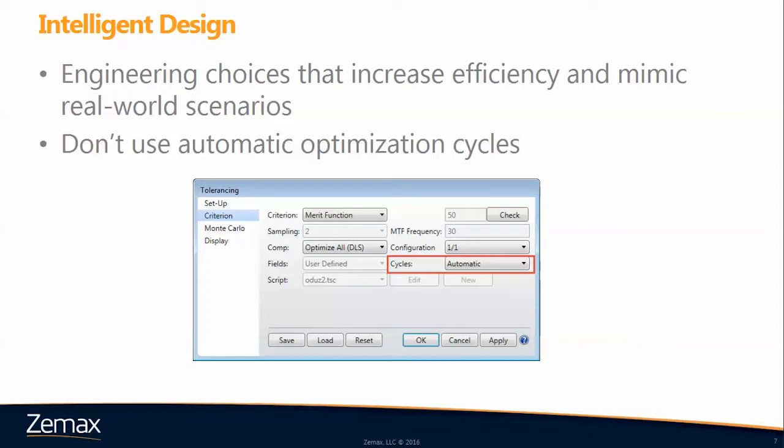And if this is set to automatic, then OpticStudio will call the optimizer in auto mode, which will run the optimizer until the optimization of all the compensators has converged. If the compensators are difficult to optimize, then a higher setting here or automatic may really increase system performance.